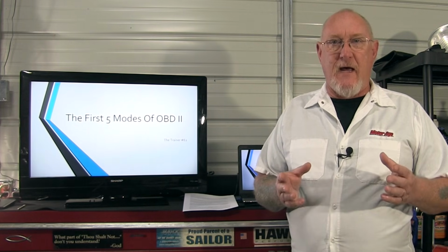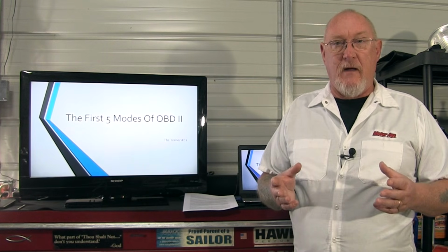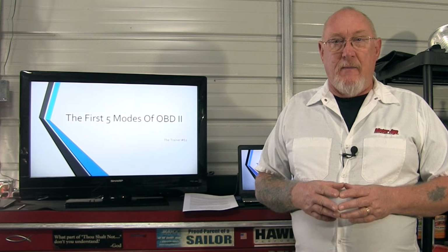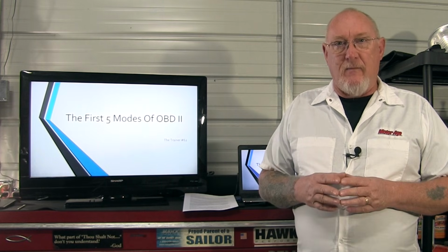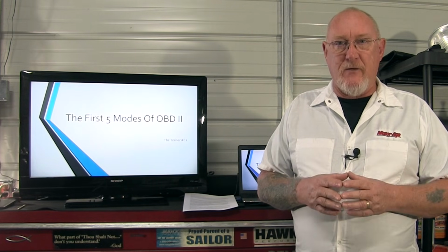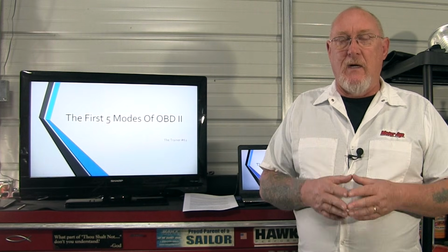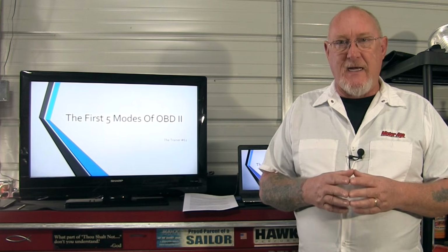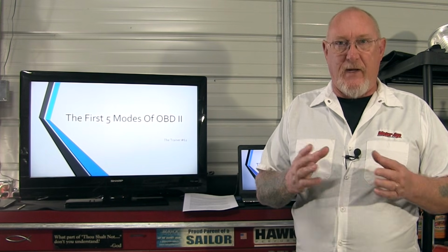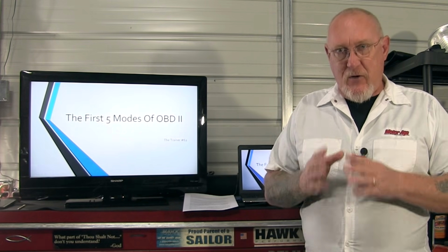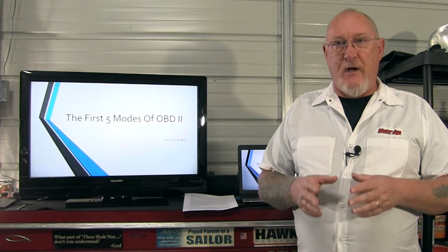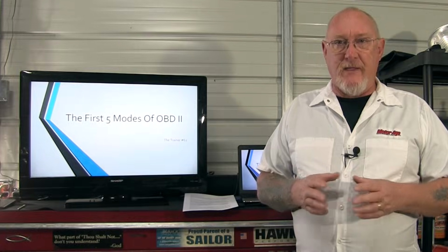Now, your shop may have a variety of scan tools on hand, from OE level tools on down to little pocket code readers, but I'm willing to bet that nearly all of them are certified to OBD II protocol, Global OBD II. If that's the case, it doesn't really matter which one you pick up. You'll be able to access the same information with any one of them. And in the majority of cases, when you're solving a DTC issue, you'll be able to solve it with the information in Global OBD II all by itself.